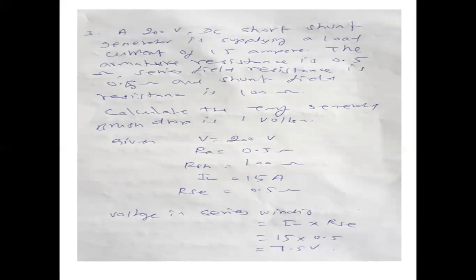We know that the carbon brush and commutator arrangement is for converting the AC into DC in the DC generator, right? So if they have given the brush drop, then we have to consider that also for the EMF equation.